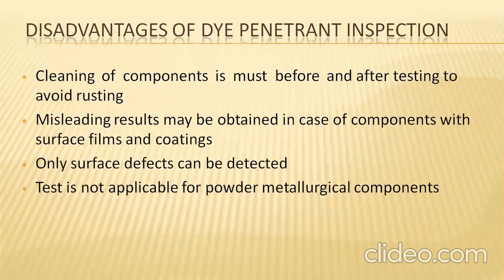It covers only the surface and the subsurface up to a particular depth. Second, pre-cleaning and post-cleaning are additional steps to be done for the inspection process. Here, direct contact is not required, but the liquid deposited at the cracks plays a very important role in identifying them.